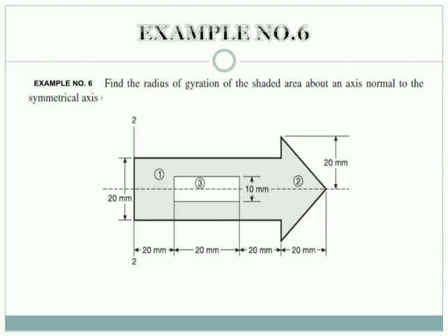In both previous examples, what we found was Ixx or IAB; both had horizontal references. Now we have a vertical reference in this figure. Then further, what is asked again? Radius of gyration. So once you get Iyy, you can easily find the radius of gyration using the formula k is equal to square root of Iyy divided by capital A.